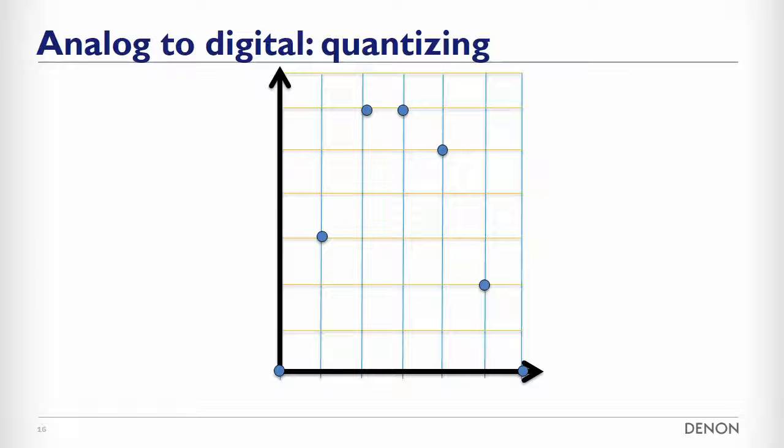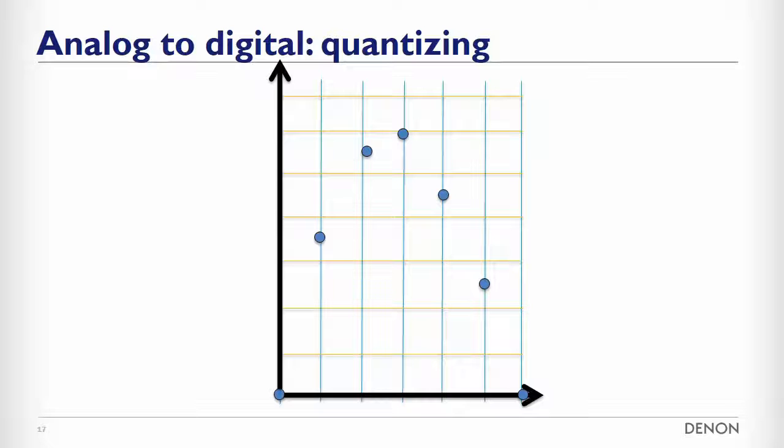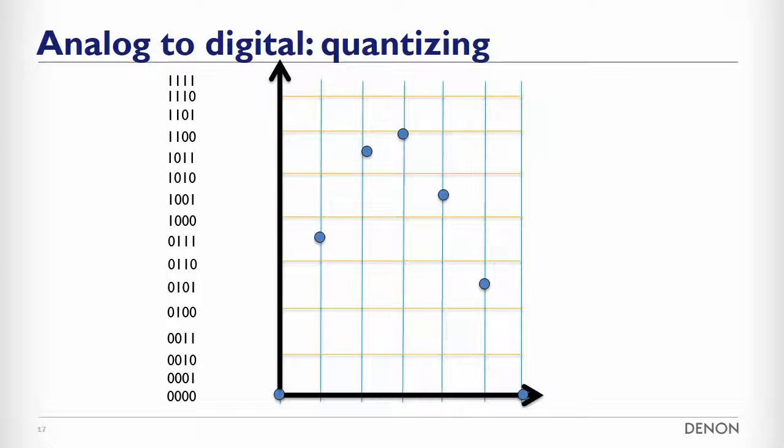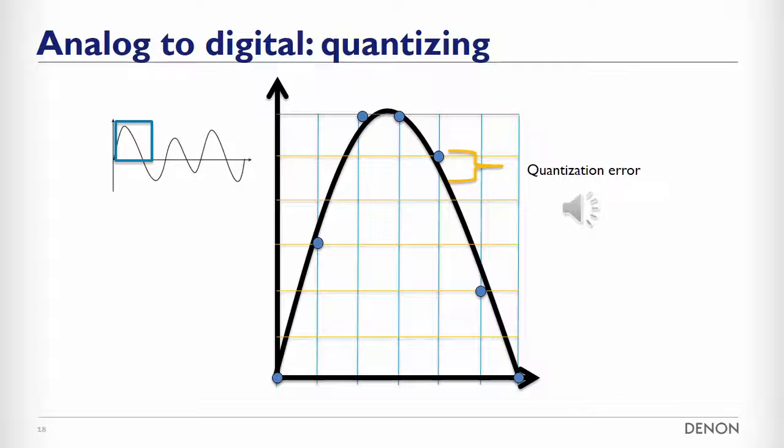Imagine that the indicated levels represent the full audio range. So in total, we quantized audio signals using 8 different levels. To represent this in bits, we need 3 bits because, with 3 bits, we can uniquely identify each level. If we were to use 1 bit more for the quantization, that is, 4 bits instead of 3, this would result in twice as many levels, so 16 levels instead of 8. With 1 bit more, you get a much more precise quantization process.